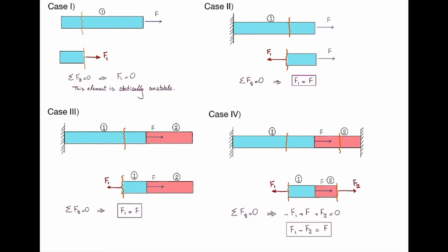So I just wanted to give you an example on the cases where the problem is indeterminate. All right, if we were in statics, this problem is unsolvable forever. We cannot determine how much is the internal force using the equilibrium equation. However, in mechanics of materials, knowing how much are the deformations, we can determine the internal forces in the element. So let's do that.